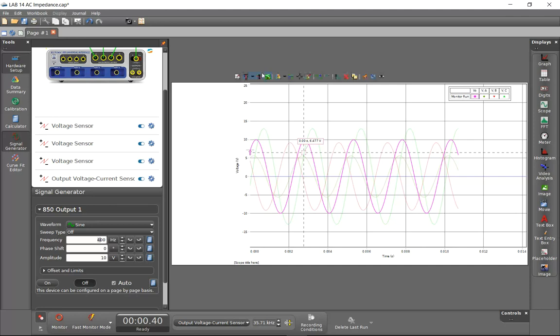And so now we see the inductor voltage there is about 8-ish. The capacitor voltage is about 13. The resistor voltage is about 6. We want to make sure that our voltages are all over 4 volts. Well, the resistor voltage, it says, needs to be over 2 volts. If the resistor voltage is too low and everything else is fine, just increase the resistance value.